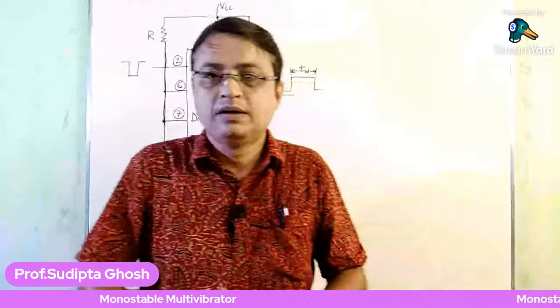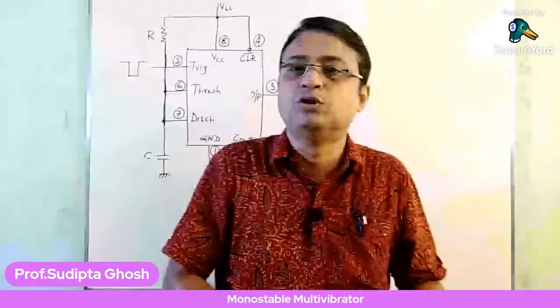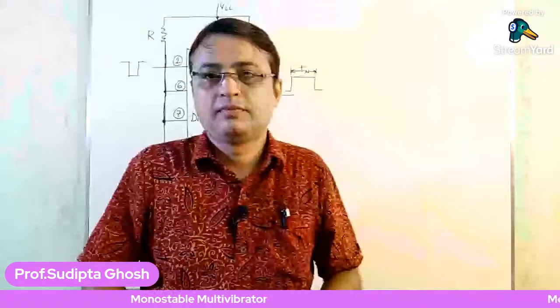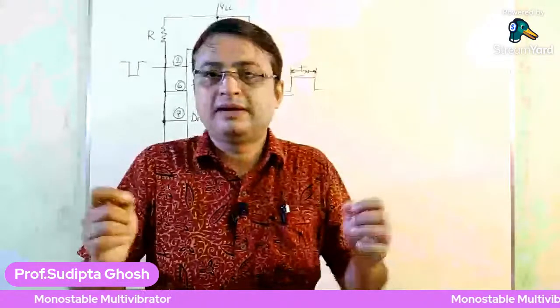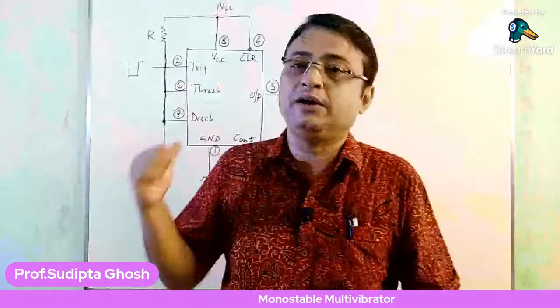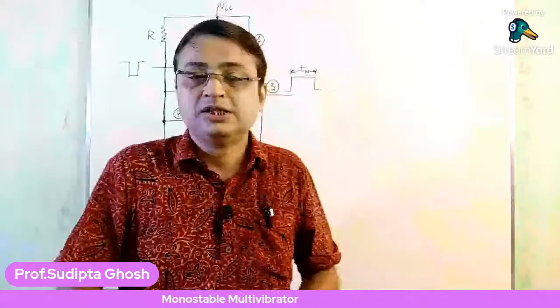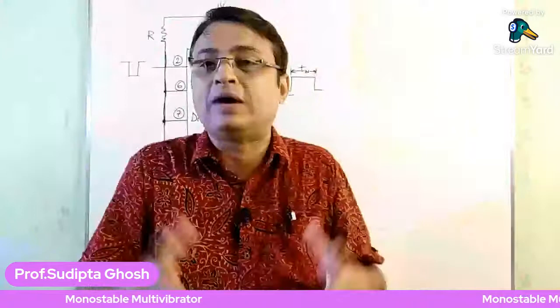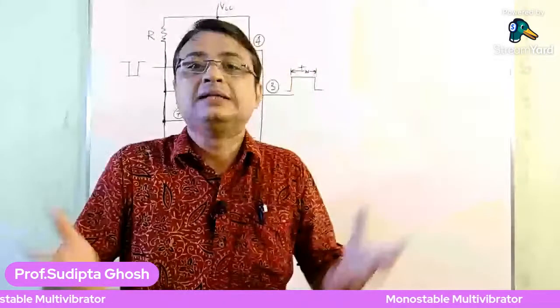You should understand why this capacitor value is 0. And actually this is the stable state of this particular monostable multivibrator. So for this monostable multivibrator, what is the stable state? The stable state is low.